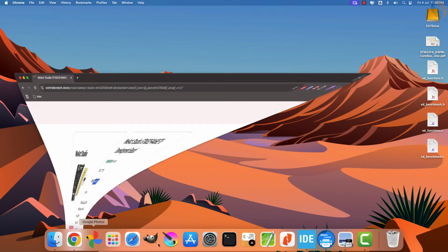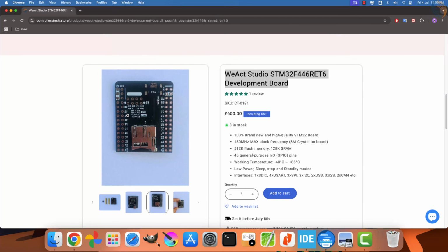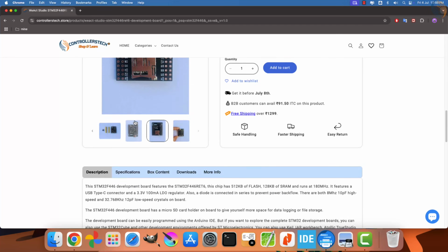I'm going to use the STM32F446 custom development board from UART Studio for this project. It's a solid board with full SDIO/SDMMC hardware support. This board has a slot for SD card at the back, which supports SDIO and SDMMC as well, meaning it's wired correctly for all modes we need.